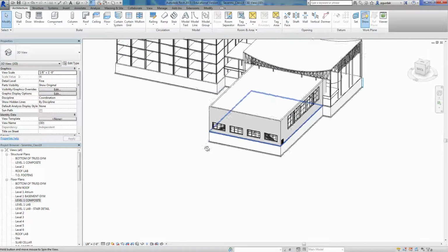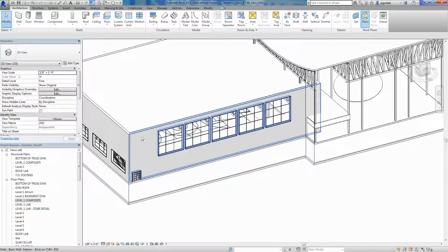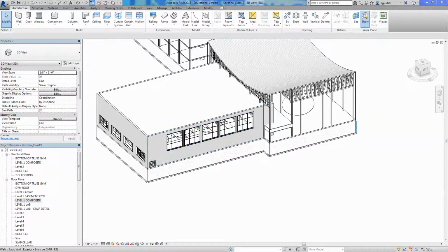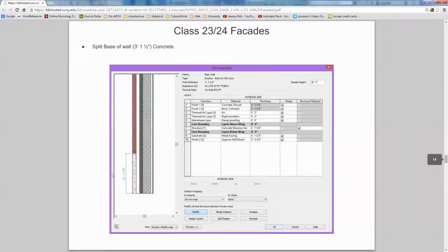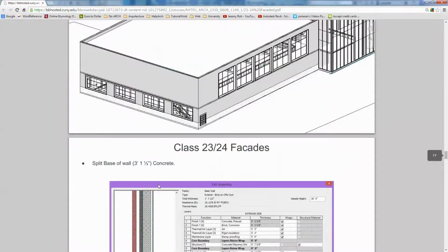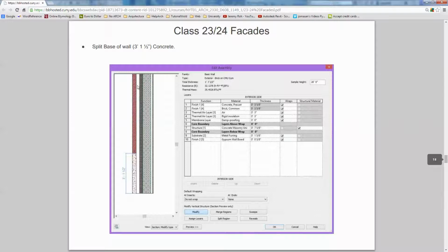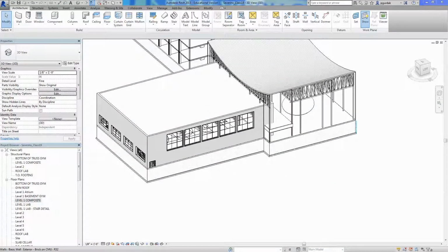Looks good. Let's do a couple of details that I think are important. Let's bring this here for a second. So let's do, for example, in the wall, split the base. So we can enter any wall and start dealing with the specificities of each of the walls. For example, how the bottom of the brick, we don't want it in brick, and we're going to use concrete to make that. So we're going to change several of those things. So let's go step by step.